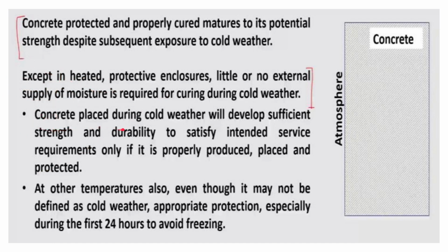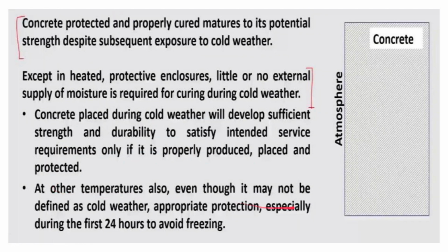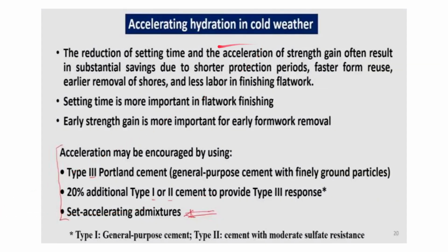Concrete placed during cold weather will develop sufficient strength and durability to satisfy intended service requirements only if it is properly produced, placed and protected. At other temperatures also, even though it may not be defined as cold weather, appropriate protection, especially during the first 24 hours to avoid freezing, is required. So let us see how the acceleration of hydration can be done in cold weather.